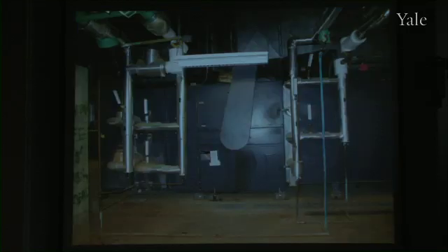Well, as far as the collection is concerned, and we're back again here at Prairie View A&M in that building, if you go down to the basement of that building, that's where you see machines like this that make the environment inside the building. This is what's called an air handling unit. And what you're looking at is a big sheet metal box. There's a fan in the middle. Straddling each side, in this particular case, are these pipes. And behind and inside the machine is a cooling coil and a heating coil and a fan. Those are the real fundamental elements. And it's this machine's job to provide a human comfort environment and to provide a suitable environment for the collections.